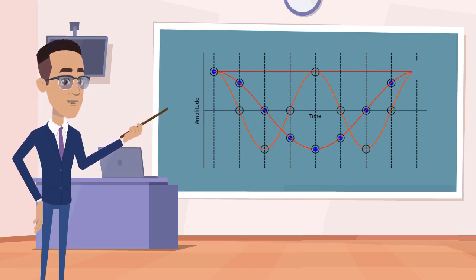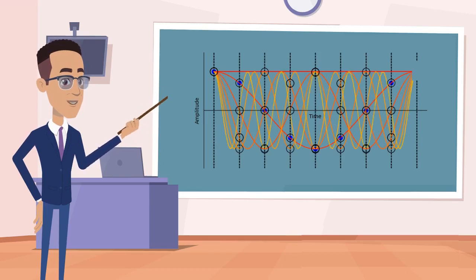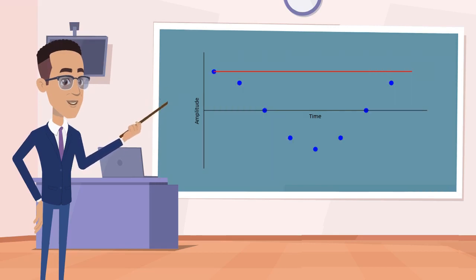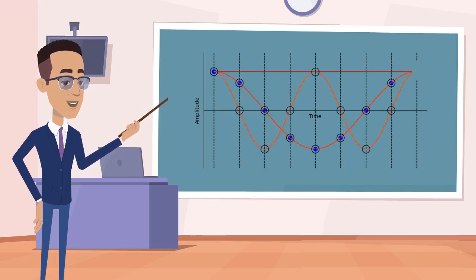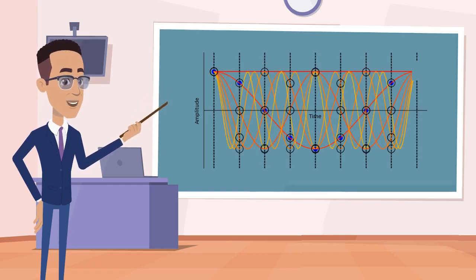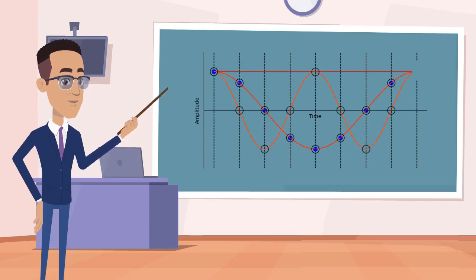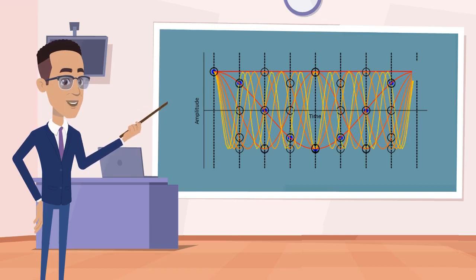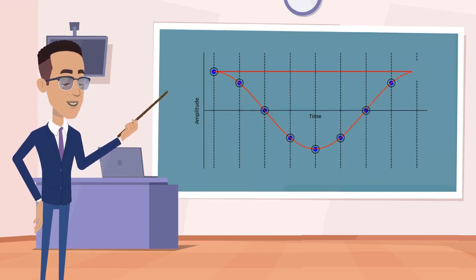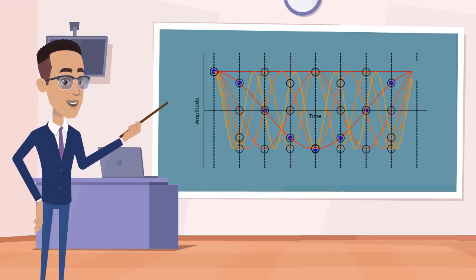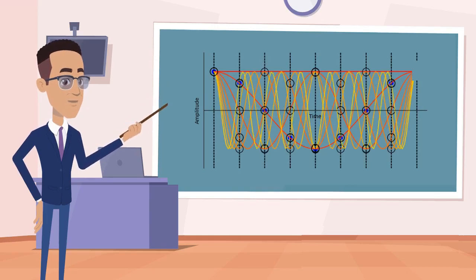But due to the periodic nature of sinusoids, these waves of different frequencies overlap in a predictable way. So, we can see sort of duplications at some data points. Therefore, instead of performing 64 complex multiplications, we need only 24. But how do we know which calculations are redundant?